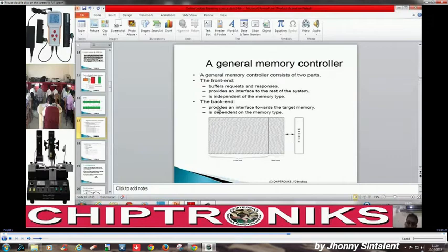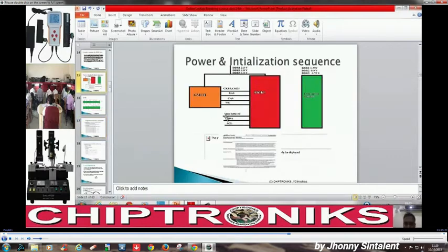The RAM SPD data and clock, the SDA and SCL signals, will be generated after the CPU is powered on, after the reset signal is generated, right? After the reset signal is generated. That is, these SDA and SCL signals are very important when you are debugging a no-display scenario.